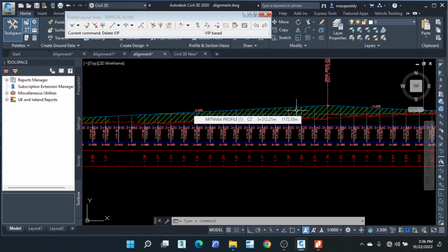There's a curve which is still stopping the levels up to there. Just select the curve itself, I mean the vertical profile, then you adjust using the PI, at the center one or either of the three. It's like bringing it towards us.